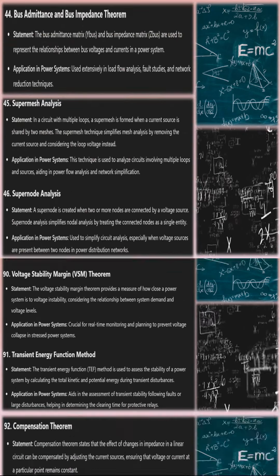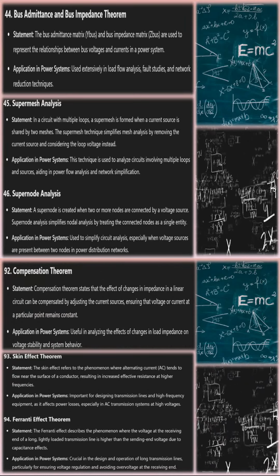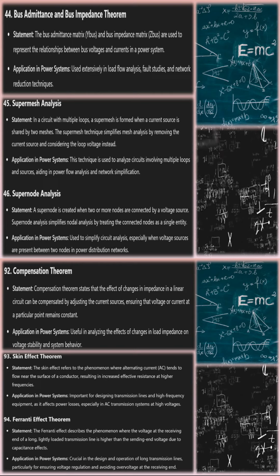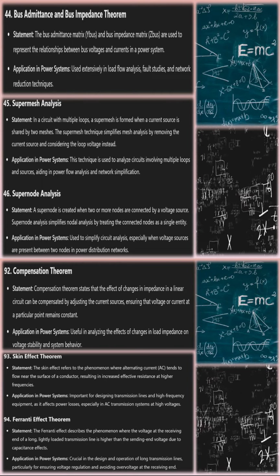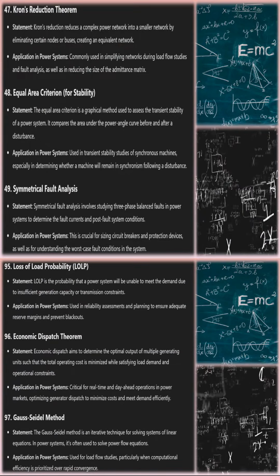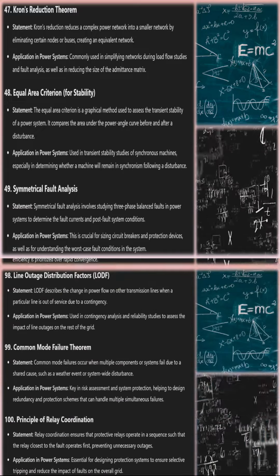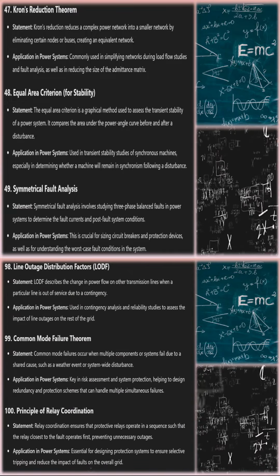Load flow theorems and algorithms. Gauss-Seidel method: an iterative technique to solve the power flow equations in a power system. Application: commonly used in power flow studies to determine bus voltages and power flows in large networks. Newton-Raphson method: a more efficient and faster converging iterative method for solving nonlinear power flow equations. Application,